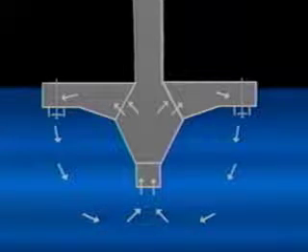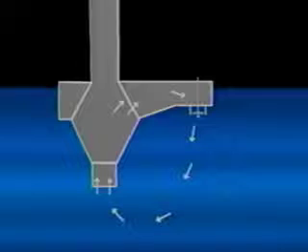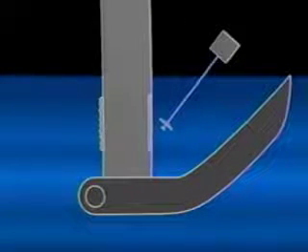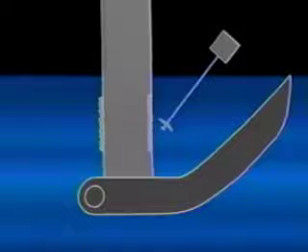The best designs provide openings, preferably screened, to allow the heated quenchant to escape the quench zone. Optimal countercurrent quenchant flow around the part facilitates uniform heat transfer as the part is dropping through the chute zone. A cooling jacket above the quench zone prevents oil or water vapor from entering the furnace. A fuming ductor located in the chute area above the cooling jacket provides further insurance against quenchant vapor contamination of the furnace atmosphere. A mesh belt of sufficient porosity and length allows for quenchant agitation around the part to facilitate completion of the quench before removal from the tank.